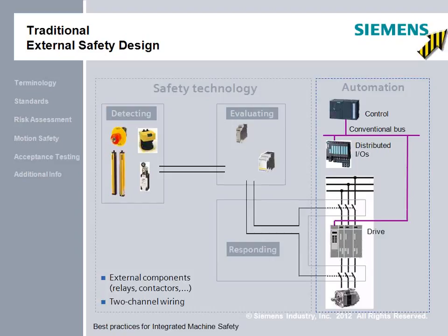This works very well in some cases. Several difficulties come into play, particularly electronic drive systems do not like contactors in their circuits. Also, we can look deeper into the machine design that this might be applied to and realize that the safest way to stop when the emergency stop is pressed may not be opening the contactors in the drive system.